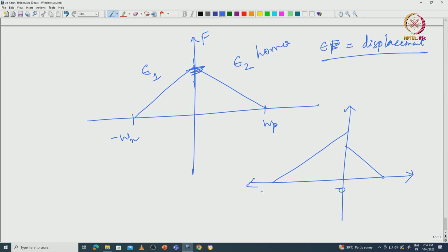So this is 0, this is maybe depletion on the N side, this is depletion on the P side. The peak electric field could be different, but the product of the dielectric constant and the peak electric field at this junction should be constant. So this could be your electric field 1, this could be peak electric field 2, and the electric field linearly decreases. Of course, there is a depletion on this side, there is a depletion on the other side, and so your total depletion width, which is Wn plus Wp, has to be modified to accommodate this fact that there are two different dielectric constants.